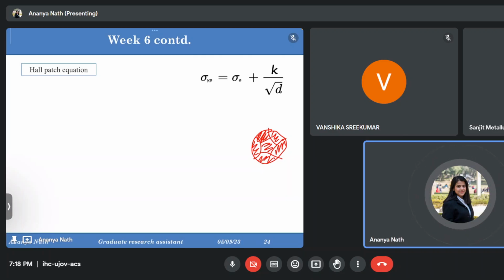This grain refinement is also dependent upon the Hall-Petch relation, which is a very well known relation for grain refinement. The dislocation pile up and the stress developed at the pile up tip due to the Cottrell barrier and all those things were discussed. There were only some formulas, nothing else. So you can go through the formulas. I think it's not that complex to read.